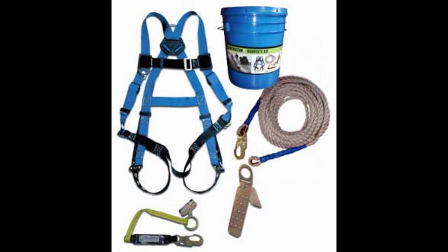We know that OSHA has determined that there is no safe distance from an unprotected side or edge that would render fall protection unnecessary. Leading edges. Each employee who is constructing a leading edge 6 feet (1.8 meters) or more above lower levels shall be protected from falling by guardrail systems, safety net systems, or personal fall arrest systems. We presume that it is feasible and will not create a greater hazard to implement at least one of the conventional fall protection systems if Plaas Incorporated employees are engaged in leading edge work.